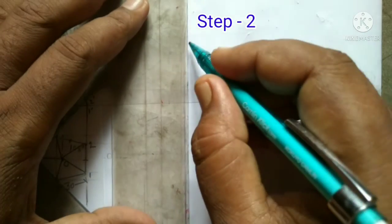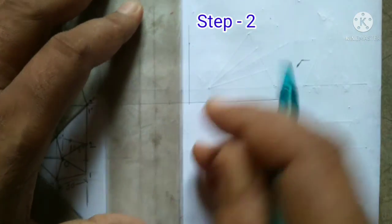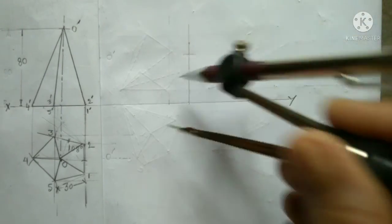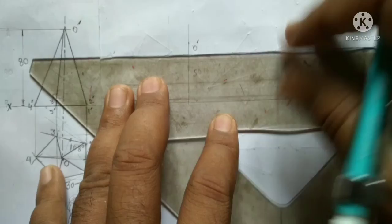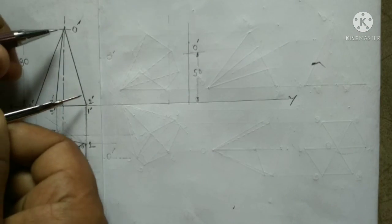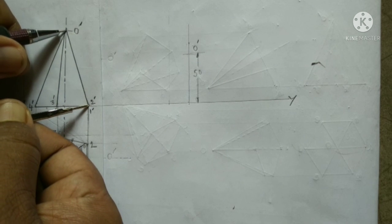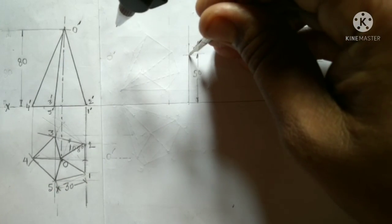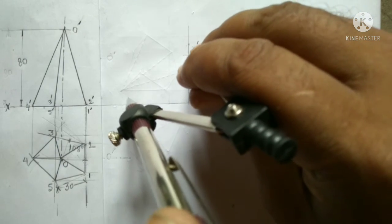Now the second step. First of all, draw a perpendicular projection line along with the ground line. Mark 50 mm distance on this perpendicular line. Take O dash, 1 dash, 2 dash distance in your compass. Draw an arc taking the endpoint of 50 mm as a center and cut it on the XY line.